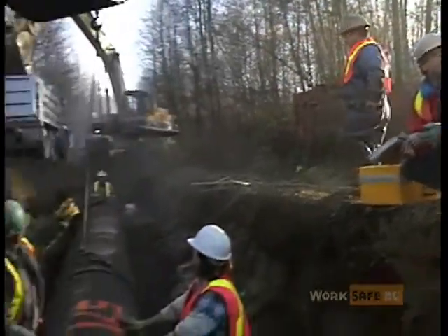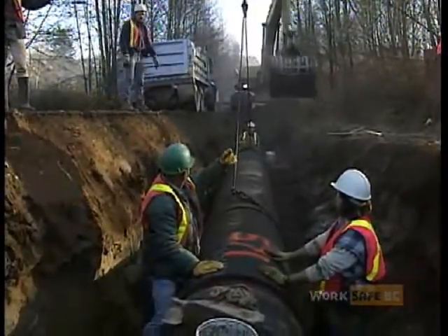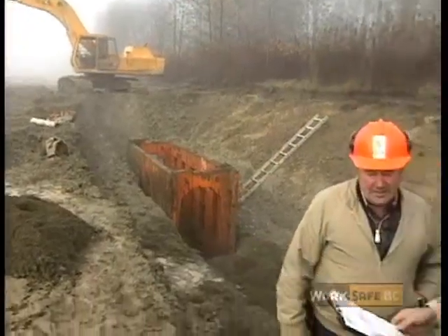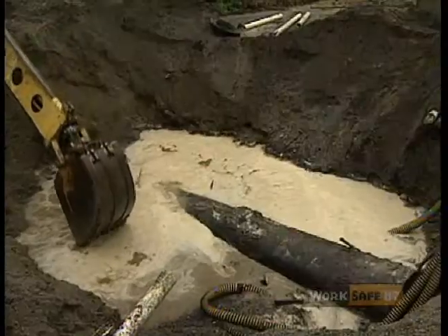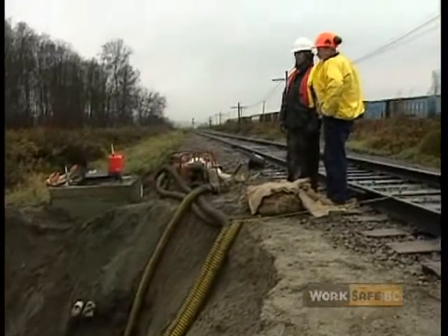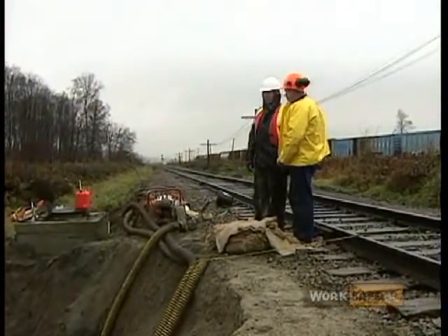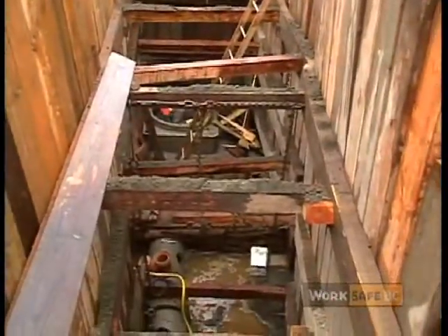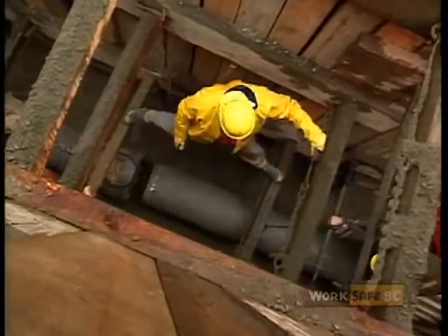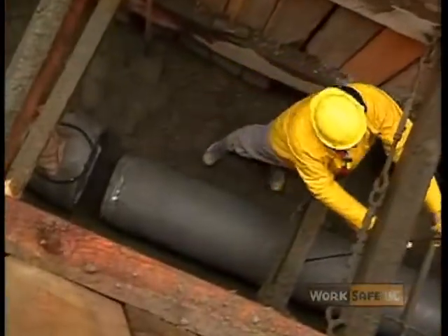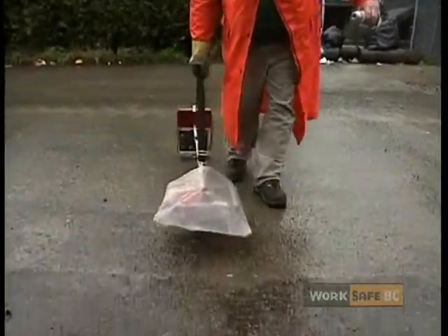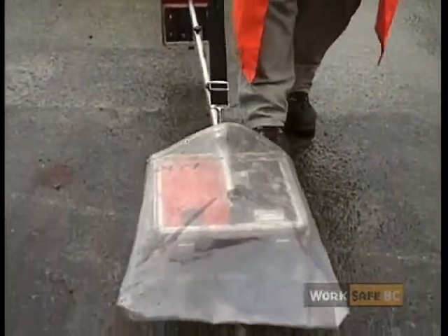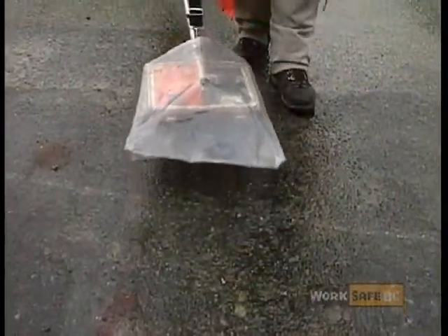There are rules that must be taken into account before work on an excavation begins. All excavation work must be carried out in accordance with the industrial health and safety regulations or with the specifications and requirements of a registered professional engineer. Utility services in the area, such as electrical, gas, steam, water, and sewer, must be located and assessed for hazard potential. Pointed tools must not be used for probing to locate underground gas lines or electrical facilities.